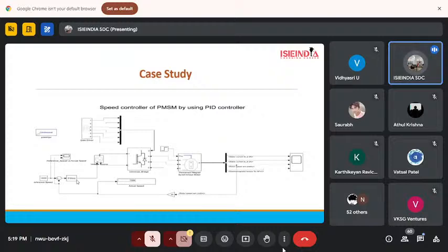So this should be like the integral, the sum of all previous errors. According to the sum of all previous errors, it finds the correct tuning value. So the KI value will take the previous errors into account and, according to that, will decrease the error to 0. And after that, the KD, the derivative value, will look after any overshoot in the signal.